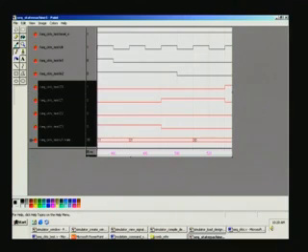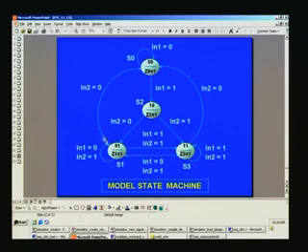And here, that is what we have from S1 to 00, provided both inputs are 0, and you can see that here, right. In fact, what is of interest is only the input being 0. So, in S1, if the input is 0, it will automatically take you here. So, we have seen all the paths. The only thing is we went to and fro, which is why it confused a bit. Otherwise, we have verified that the whole functionality is intact.